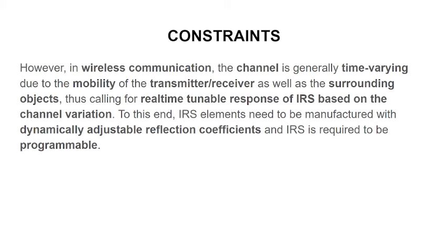Constraint of IRS. However, in wireless communication, the channel is generally time varying due to the mobility of the transmitter and receiver as well as the surrounding objects, calling for real-time tunable response of IRS based on the channel variation. To this end, IRS elements need to be manufactured with dynamically adjustable reflection coefficients, and IRS is required to be programmable.